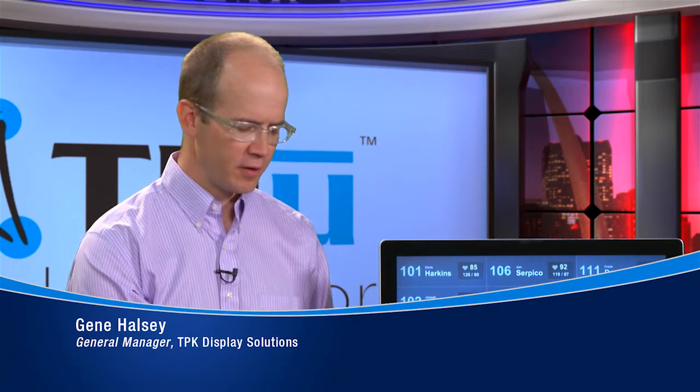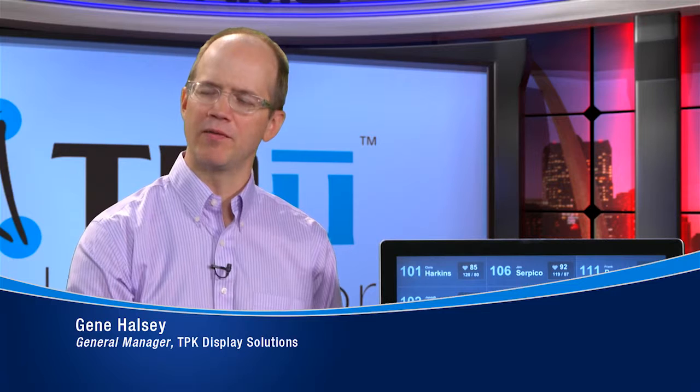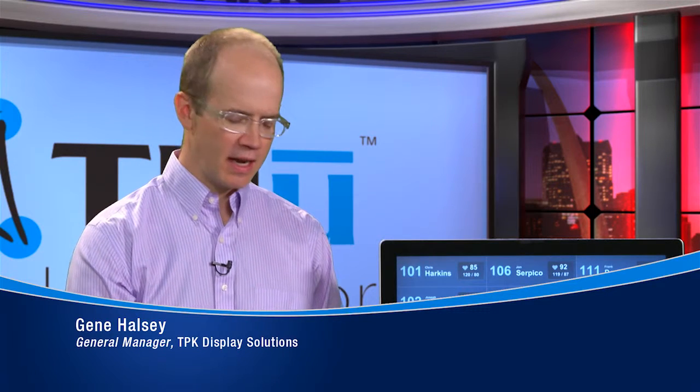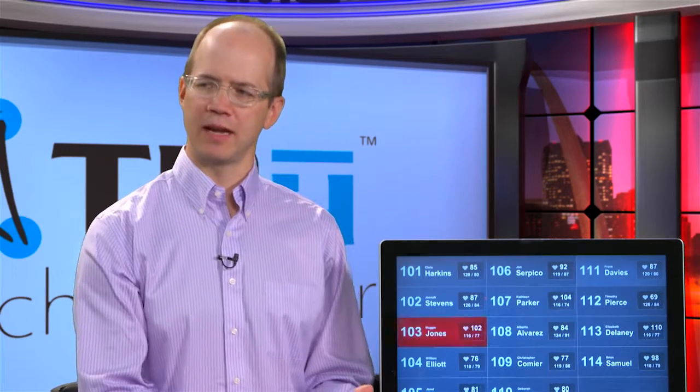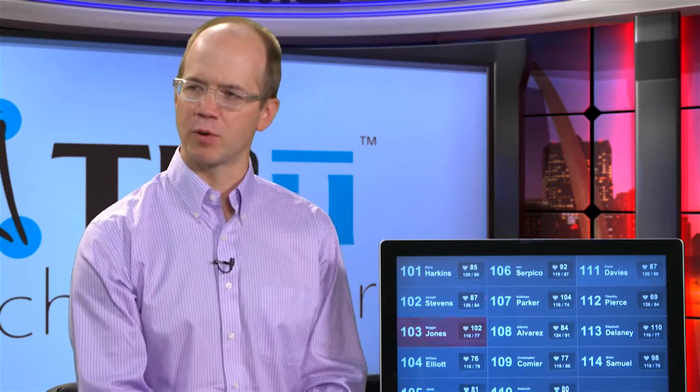The nice part about PCAP is it's a glass-based technology. So your touch surface on a PCAP is still going to be a very robust glass surface. And if I take all those electronics and bury them behind at least one of those layers of glass, I don't have to worry about damaging the electronics. A lot of the other technologies that are out there, single touch and even multi-touch technologies, you can do damage to the surface that'll impact how the screen works. With PCAP, you don't have that concern. You can still break a PCAP screen, I mean, you can go out there and break it, but the point being, it takes a lot more to break it than comparable technologies.